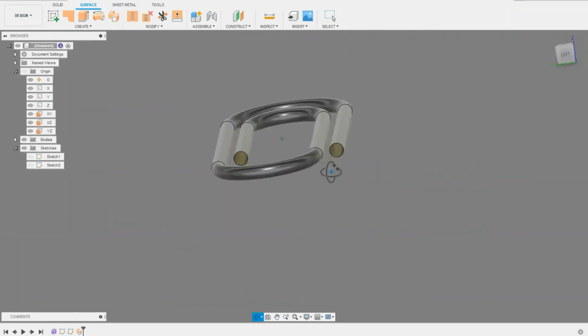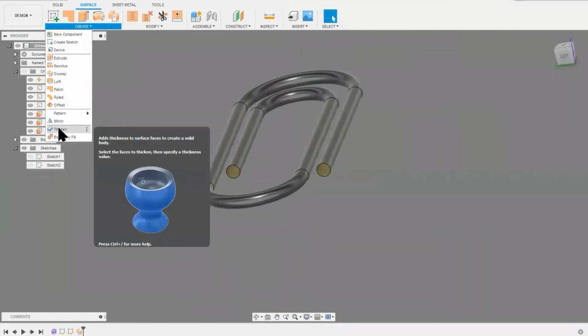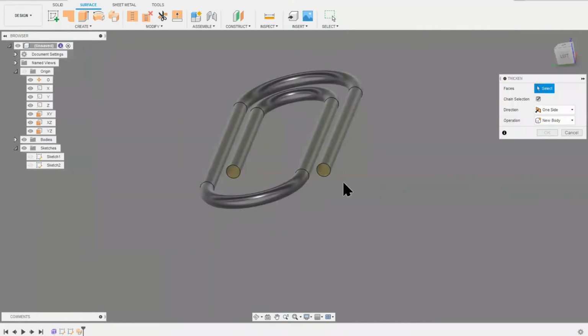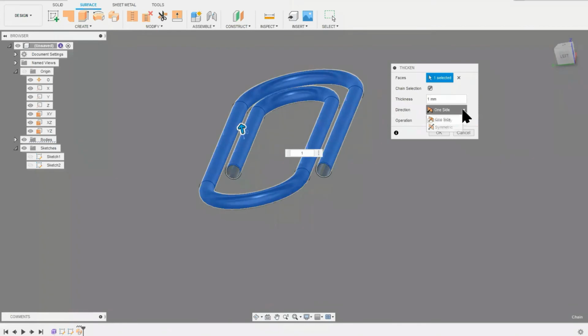Now, one of the really clever things that I can do with Fusion, and look, this would be the same for a lot of tools, and Inventor has this same functionality, is we can use a thicken command to add material thickness to our model. So you can see in here, if I pop in that I want to make this into a hollow, but rather than being a zero thickness item, I can thicken it to whatever thickness I would like, and either on the inside or the outside, so we can flip that particular functionality over.